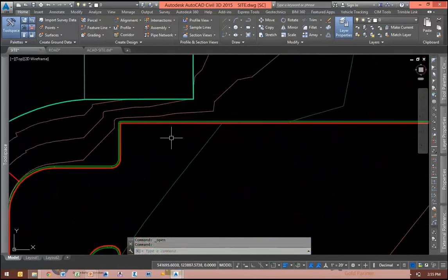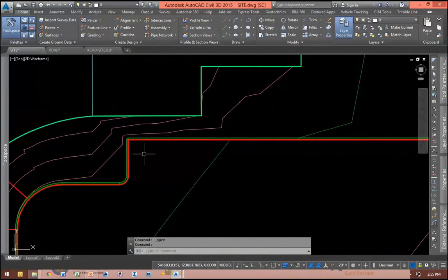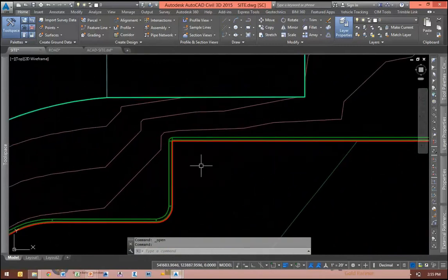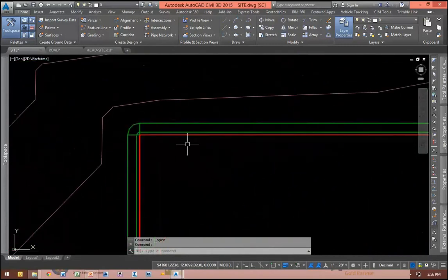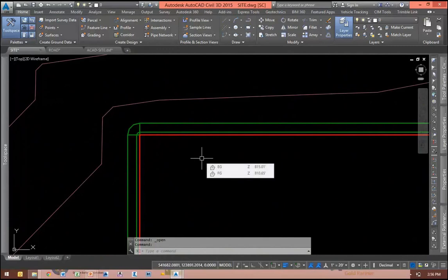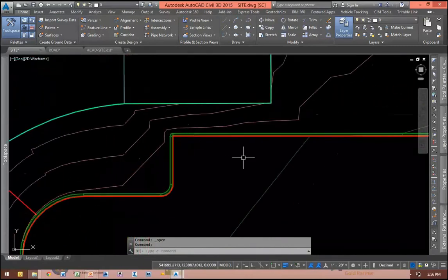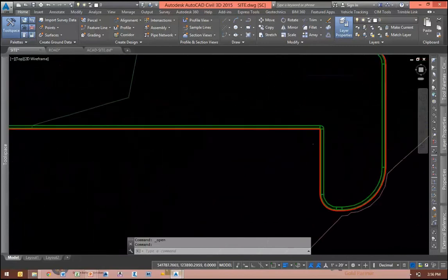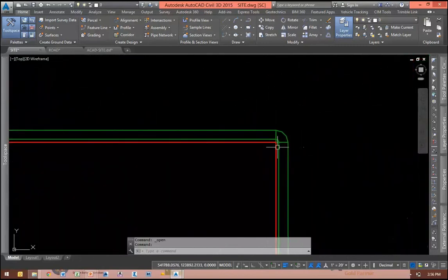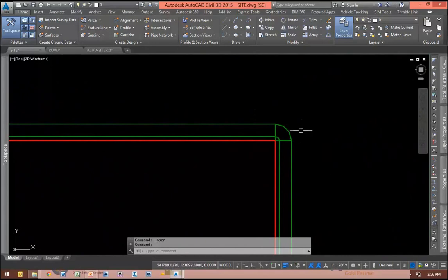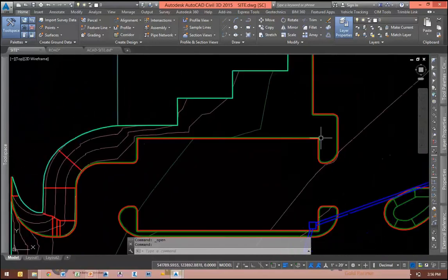Next thing, we're dealing with feature lines and curb gradings in Civil 3D. They might be grading these in different ways. In this case, I have some grading objects. We might have been using some stepped offset feature lines, for example. A lot of times what we're wanting to stake is back of curb. Any of you guys who are using grading objects, you get this little loop-de-loo thing here, right? And you want to stake this right here. So what's the simplest way?